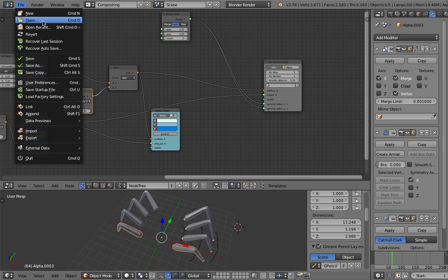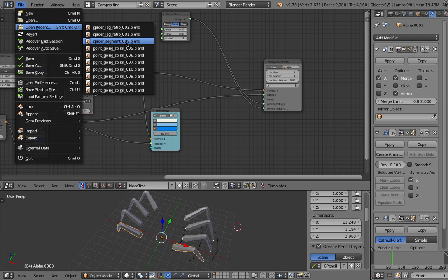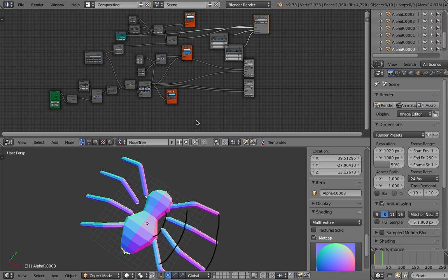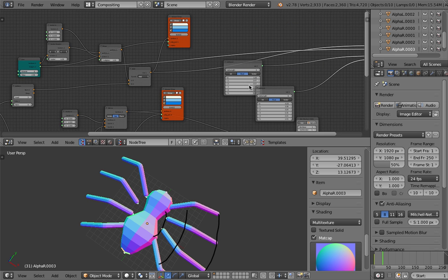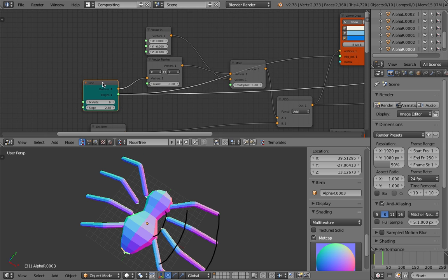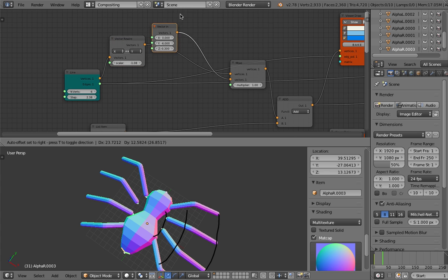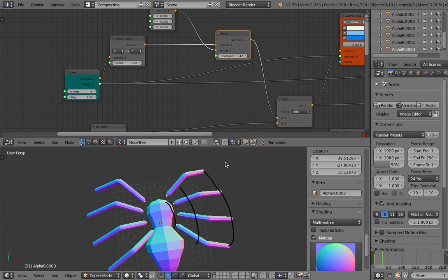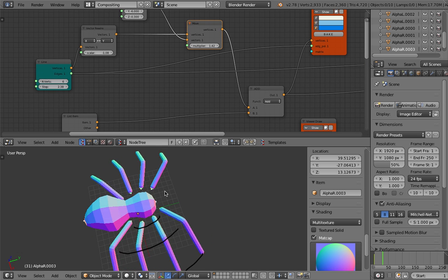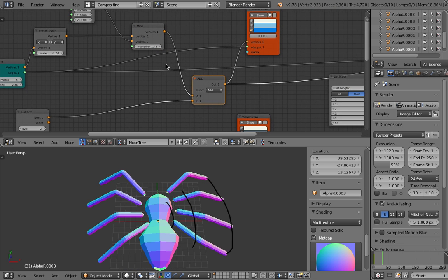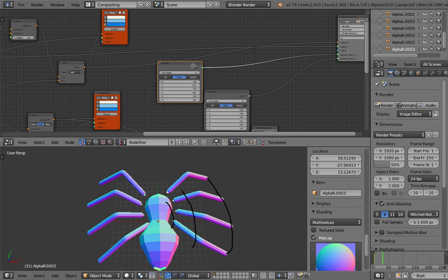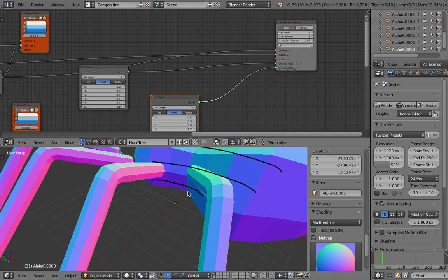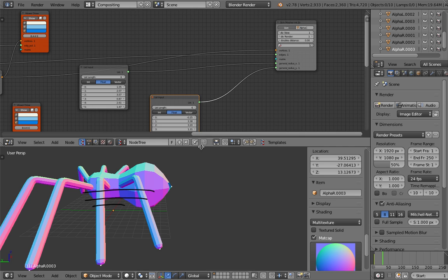The body part, you kind of already know how to do it. I open my example here. So with the body part, basically it's a single line and being rewired with vector in, and then I move it just to place the spider properly, something like that actually. That's kind of close. And then I'm using skin modifier and list input for the segment to generate this body part. Spider actually,